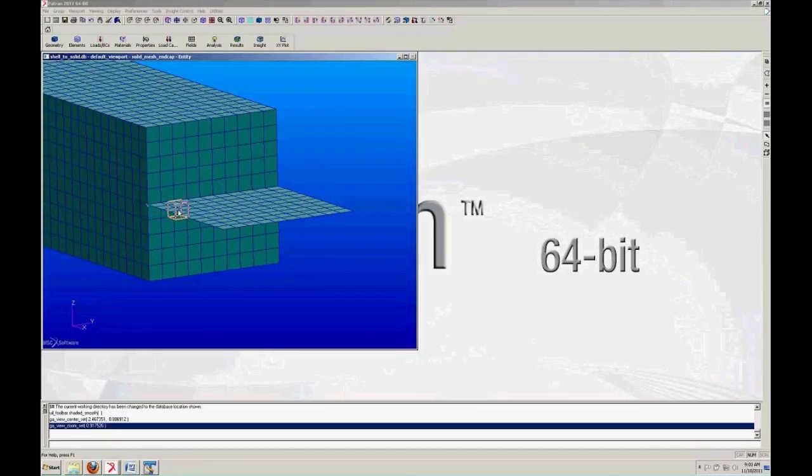However, the problem is that if you do a shear and bending diagram, the bending diagram should show zero bending moment here and then show maximum bending moment here. And this is where you should get the highest stresses. However, if you put a shell element inside here, your bending moment will actually go down and then somehow magically increase inside the solid. Some people argue that is what happens in real life, but for me, I prefer a conservative model. So I don't like putting shells inside the solid.